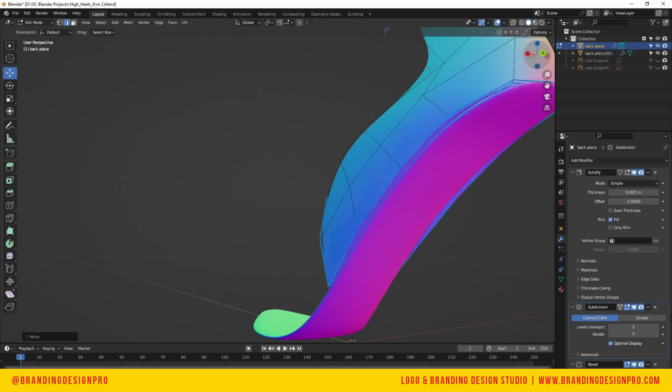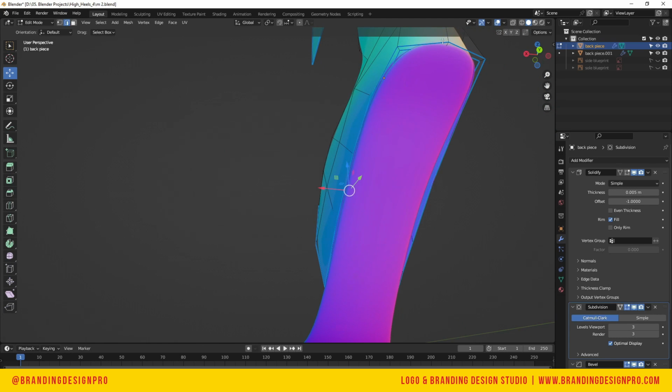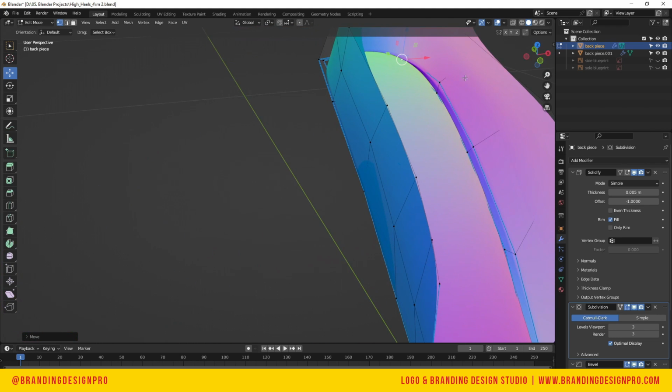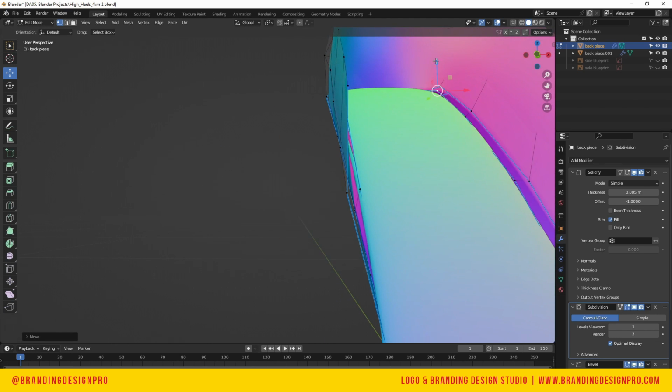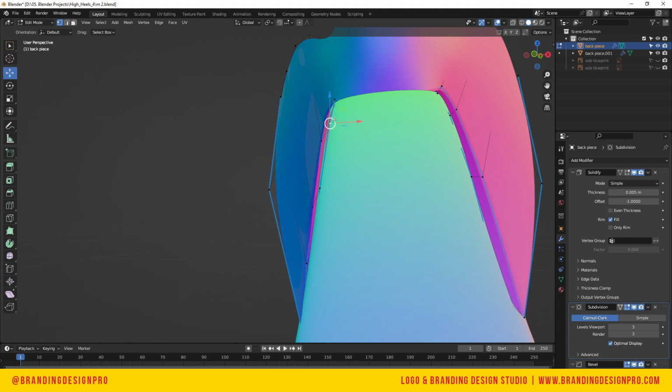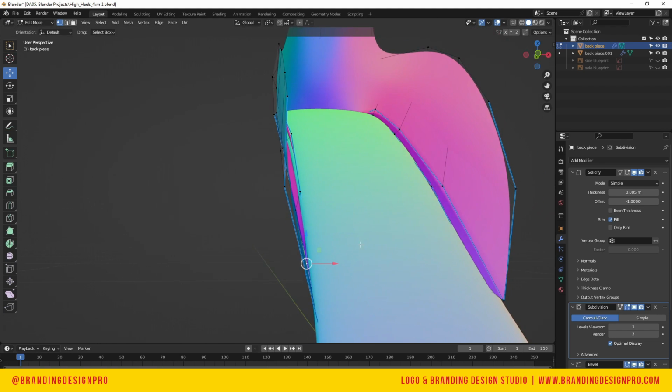All right, and from there I'm gonna go to vertices and kind of just adjust that one inward, GX, GY. There you go. So now you're gonna notice that they're sticking up far above the sole. That's not a problem because no one's really gonna see that close inside of the shoe. We could add an extra edge on top of that, but then that's even more vertices we have to manipulate. And for the sake of time, I'm not going to do that. This is good enough to help us with this presentation that we're putting together.